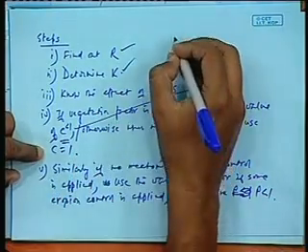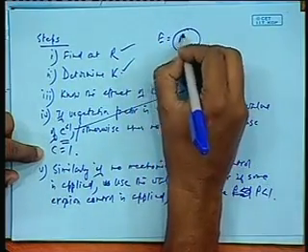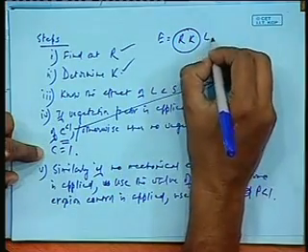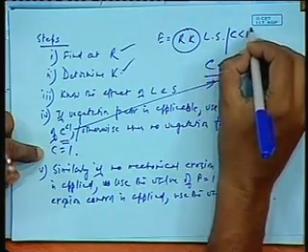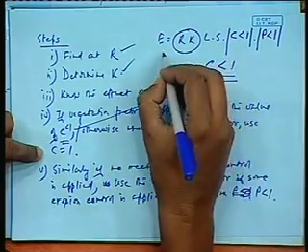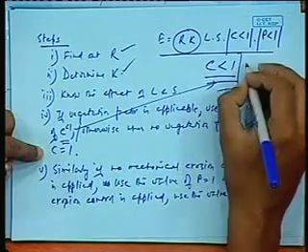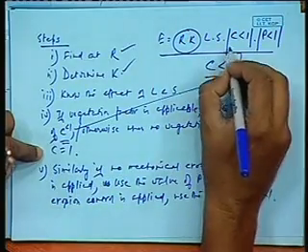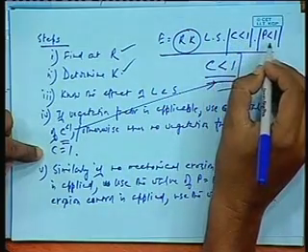So, what is in effect happening here is this, see this E, this is the basic value RK that I have said. Now, if it is say LS, also you would find out LS. Now, suppose we are using C less than 1 multiplied by P less than 1. So, what is happening here is that the total erosion potential has been reduced because these are less than 1.